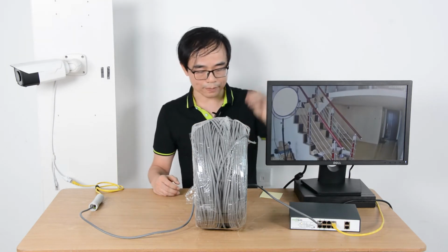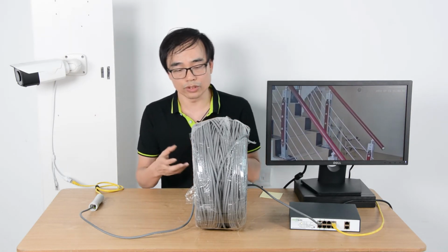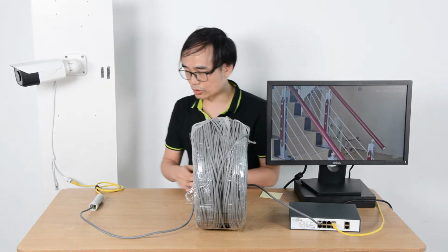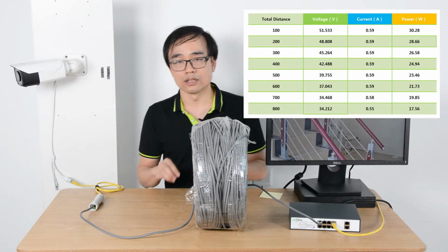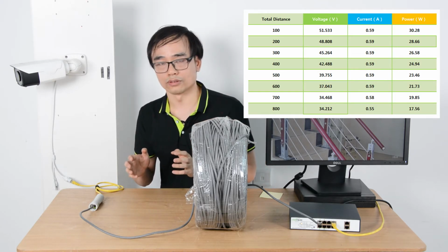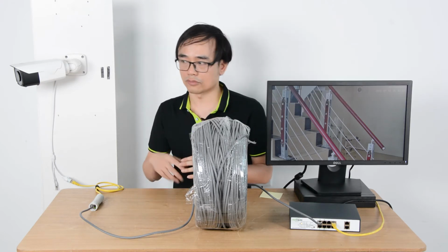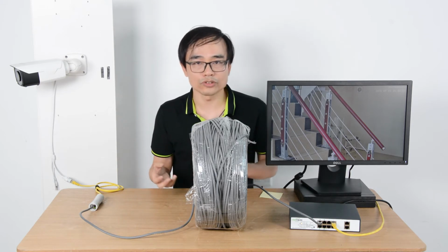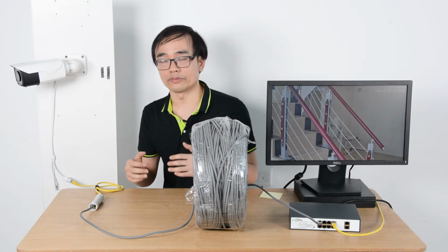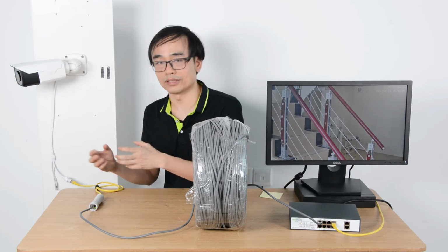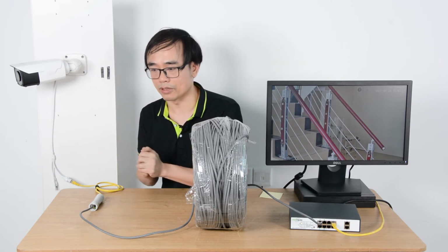The second thing will be the power budget. Once power transmits through the Ethernet cable, there is always power loss. The power will be converted to heat and lost. So the power budget within 500 meters, we still have about 23 watts. Wow, it sounds crazy, right? Because PoE and PoE Plus can only supply 25 watts within 100 meters. Why can this one have about 23 watts after 500 meters? It's enough to supply most infrared IP PTZ cameras, pan-tilt-zoom cameras.